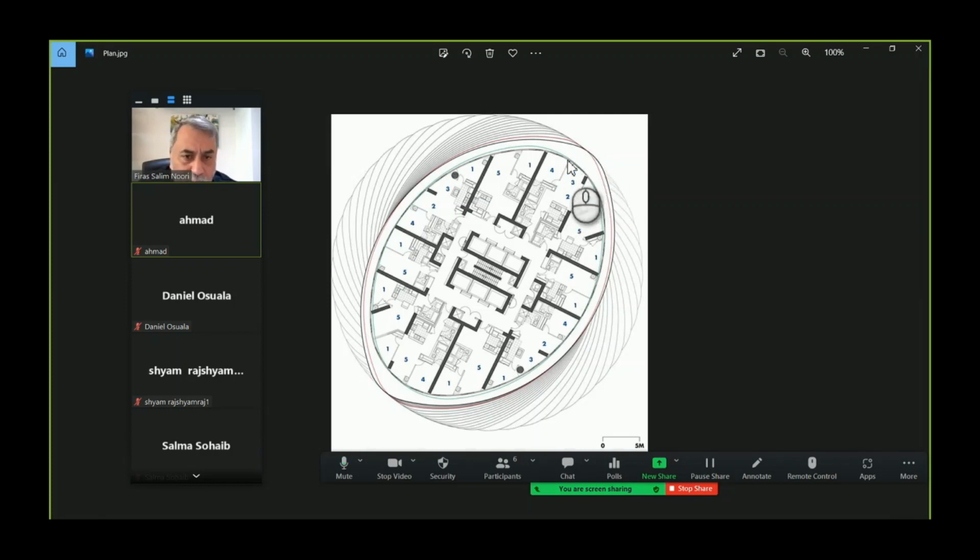Now the problem we're facing, we need to put this in Revit. The problem we're going to face is that you have to bring this image inside Revit and scale it. So you have to put a reference, a reference line, and then on that reference or that line you have to go to make scale reference, so you can scale the image. You will turn the image from its unknown scale into an image to scale. That will help you.